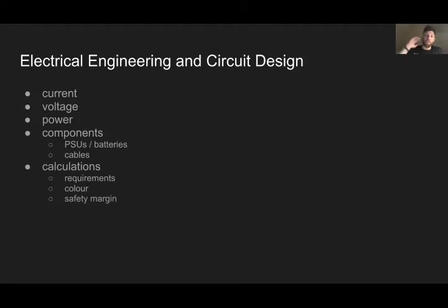So always calculate your maximum possible power requirements and add 10% on top of that to get your safe quantity of power that you need to supply, or conversely, calculate the amount of power you've got and then subtract 10% of that to get the amount of power you're allowed to use and ultimately the number of LEDs you're allowed to hook up.